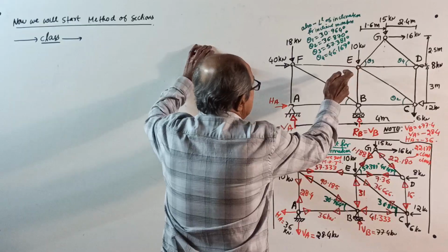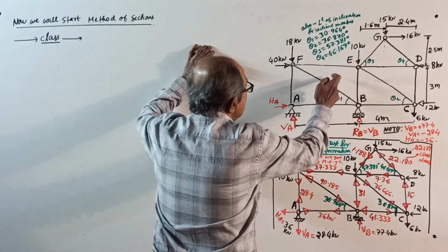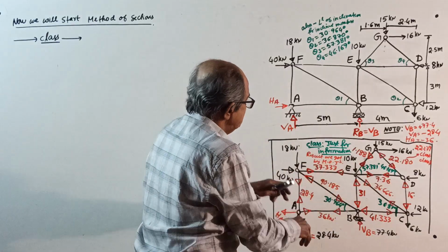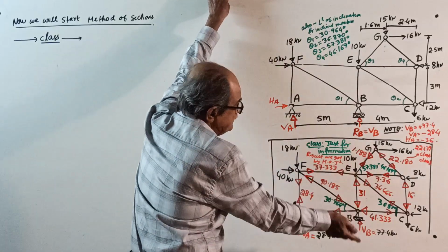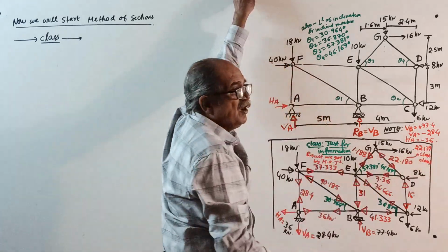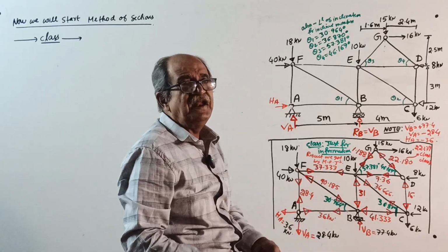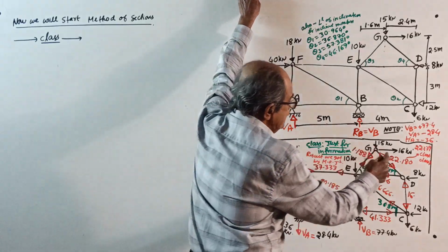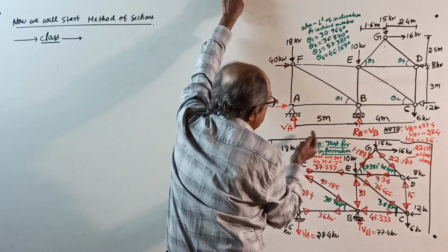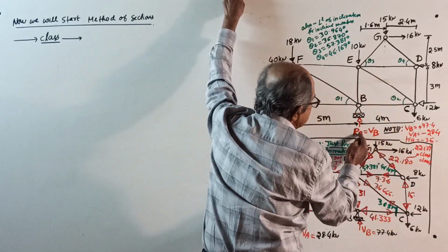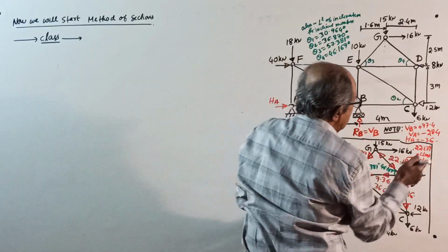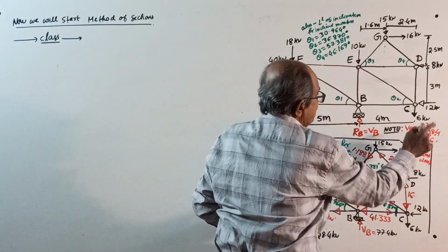Remember, this is the sketch used, you can consider this as a star sketch for method of joints. This is just for information. Everything is correct. Last class, I wrote 22.179 because of rounding off error. Today, since I did it in the calculator, that error reduced. It became 22.180. That is not a problem. Also note, we got VB plus 77.4 kilonewton, VA minus 28.4 kilonewton, and HA minus 36. Remember it.